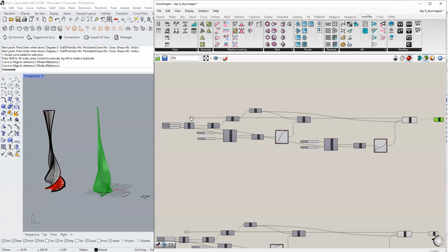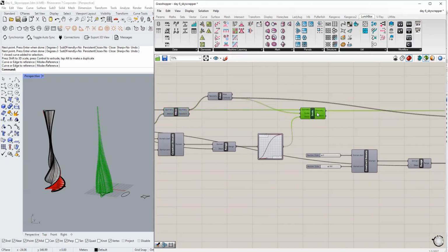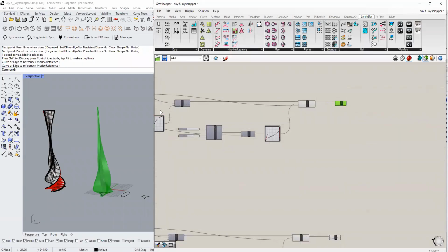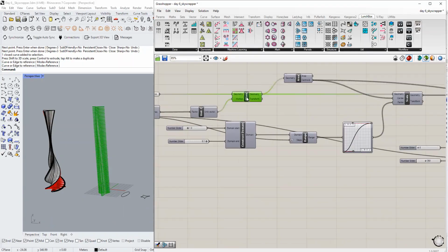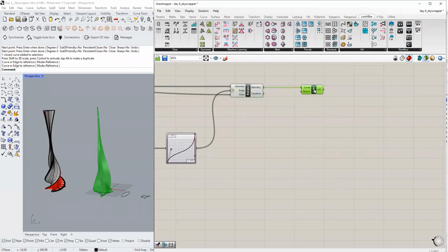So in terms of primary steps, you have the flow plate imported. You move it to create multiple flow plates, scale it to give varying sizes, rotate it for varying angles, and then loft it. Definitely you'll be using range and graph mapper every now and then, whenever you need multiple numbers to be generated. But the key steps in the algorithm are multiple flow plates, scaling, rotating, and then lofting. That's it. Try it out.